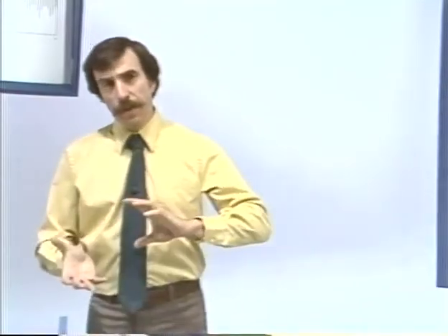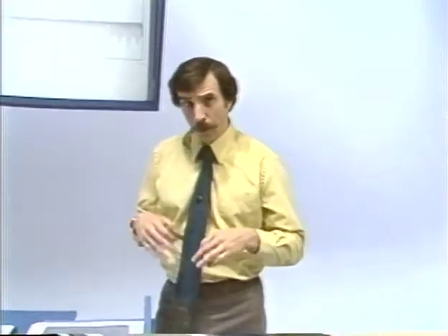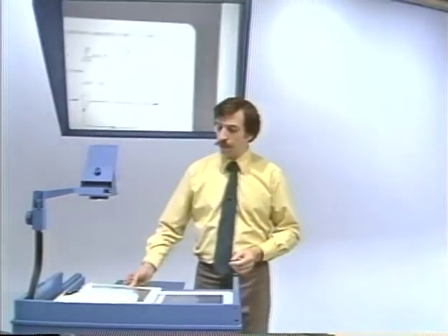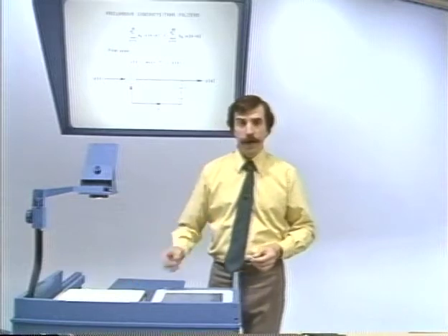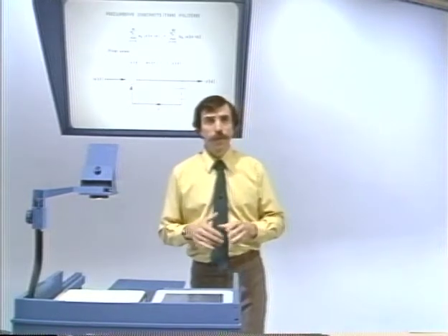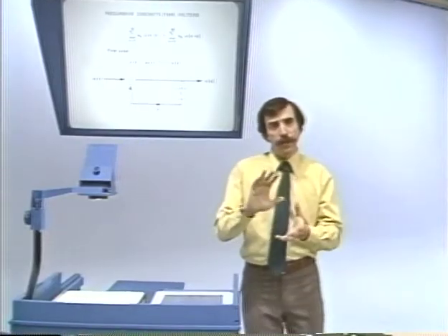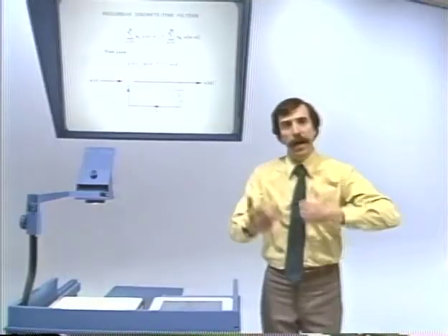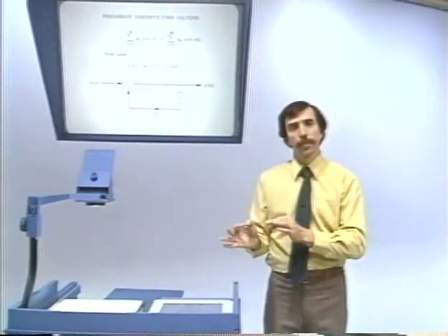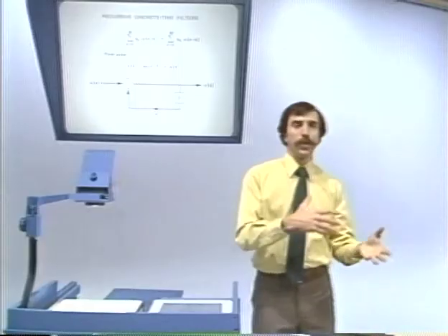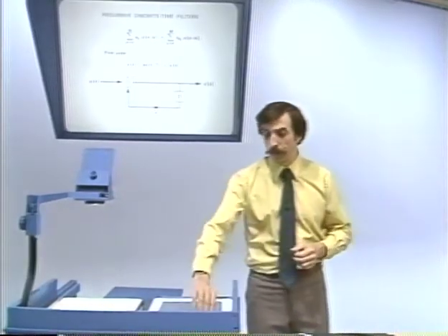All right, so we've seen moving average filters, or what are sometimes referred to as non-recursive filters. And they are, as I stressed, a very important class of discrete-time filters. Another very important class of discrete-time filters are what are referred to as recursive filters. Recursive filters are filters for which the difference equation has feedback from the output back into the input. In other words, the output depends not only on the input, but also on previous values of the output.